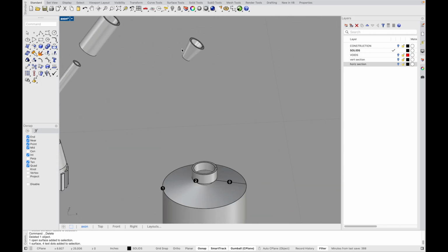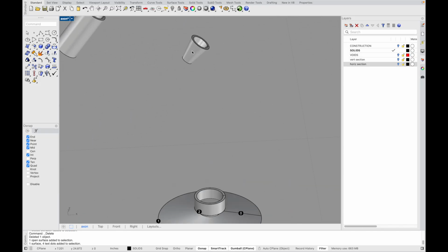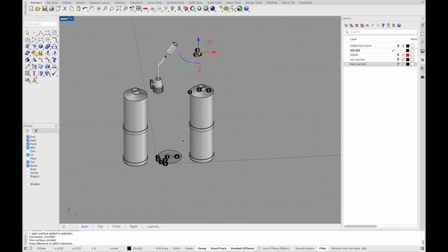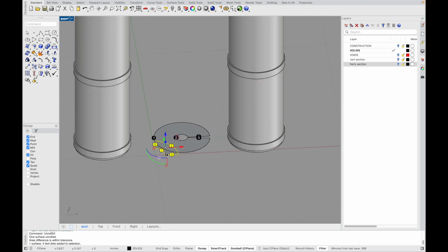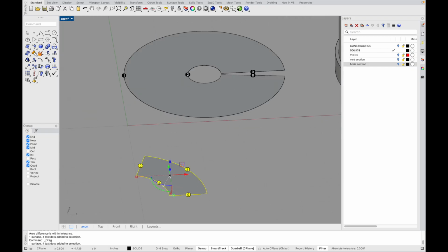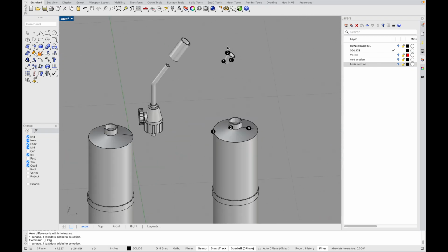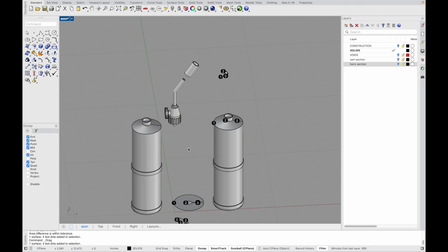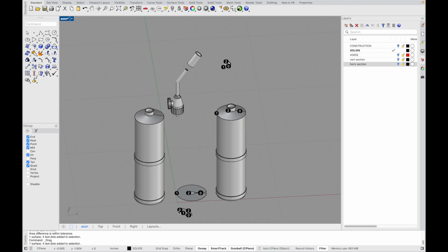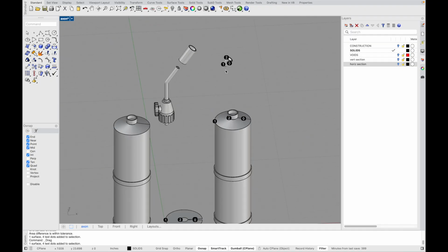So, another shape that's really hard to, that's not obvious how to make is something like this. So unroll surface, okie dokes, check this out. There's that thing again. Now it kind of dumps these things in the same spot every time, so you might need to move them. But this guy is that cone unrolled and flattened. So if you need to know how to cut this piece of paper out with a laser cutter or with an X-Acto knife or whatever to roll it into that shape, that will do it.